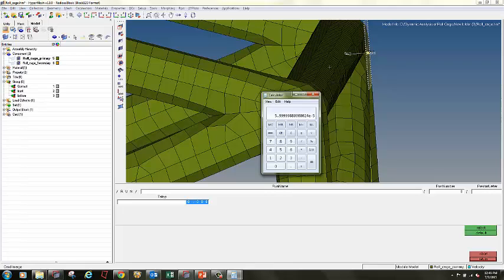So this is from 0 to 10 millimeter and bounce back. So it will travel 20 millimeters, but for the safer side, I am calculating a 40 millimeter solution. So I will multiply this by 40. So this is my runtime, that is 0.002 seconds.